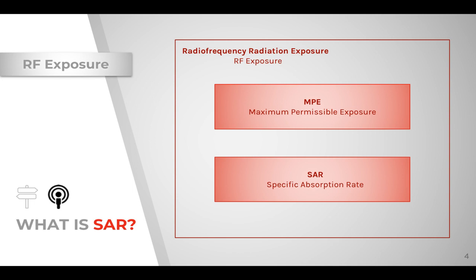At the very core, the limits are defined by the SAR limits, but MPE limits are derived from the SAR limits in terms of field strength and power density. So basically, it's based on SAR, but MPE limits are more relaxed. MPE limits apply to transmitters operating in the frequency range 300 kilohertz to 100 gigahertz, and for SAR compliance we use SAR limits for up to 6 gigahertz. So yeah, SAR compliance is between, I think, 100 kilohertz to 6 gigahertz.